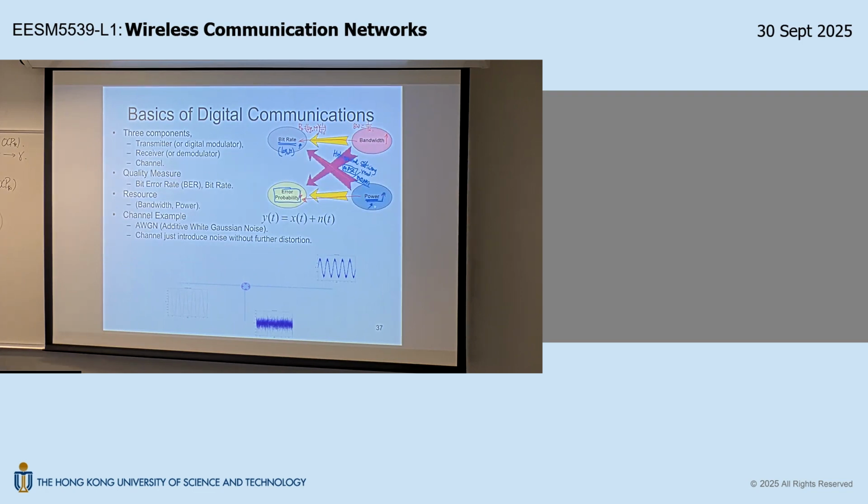And it's not just naively increasing the modulation level. So the data path design will have a different design compared to the conventional one. The reason is because when you need to operate at 4096 QAM, the operating signal-to-noise ratio will be super high. Under such high signal-to-noise ratio, a lot of issues which were not issues before now become significant issues. For example, phase noise, synchronization error, all these kinds of effects. So it will require a different design.